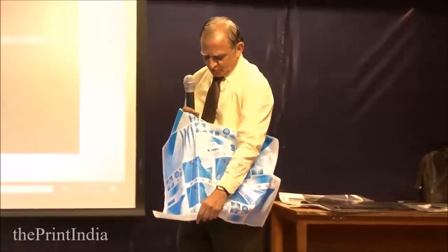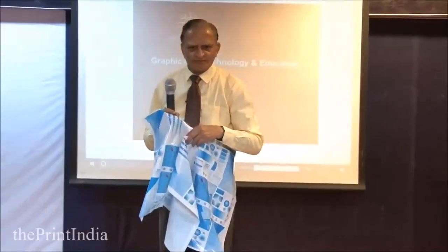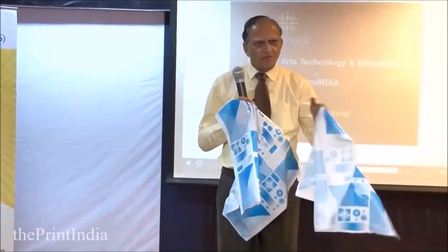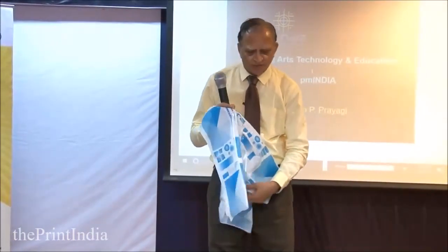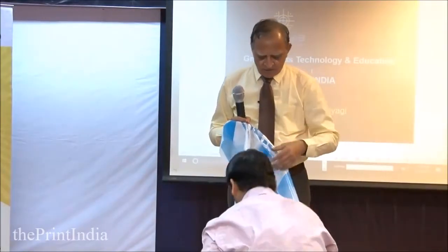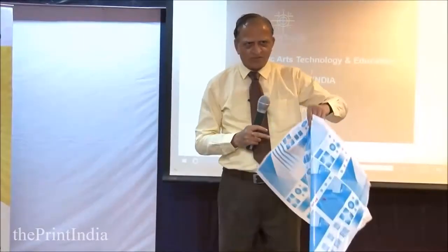Here I have samples of two Flexos with a change in anilox roll. So with one anilox you are getting better gradation, with smoother vignettes as compared to the other. So that gives you better color, smoother gradation. Maybe we can also discuss it later.